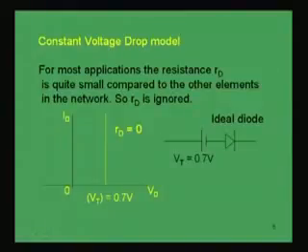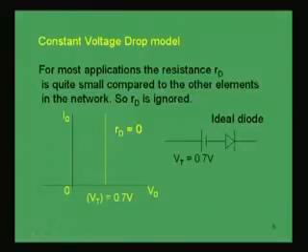So, the model becomes much simpler, and in the cases where the calculation of current is not so important and only the application of diode is important, for example, in rectifier circuits where we are concerned about the effect of using the diode, not the exact calculation of the currents as such, then we can use this model, and this is mostly used in those cases. And